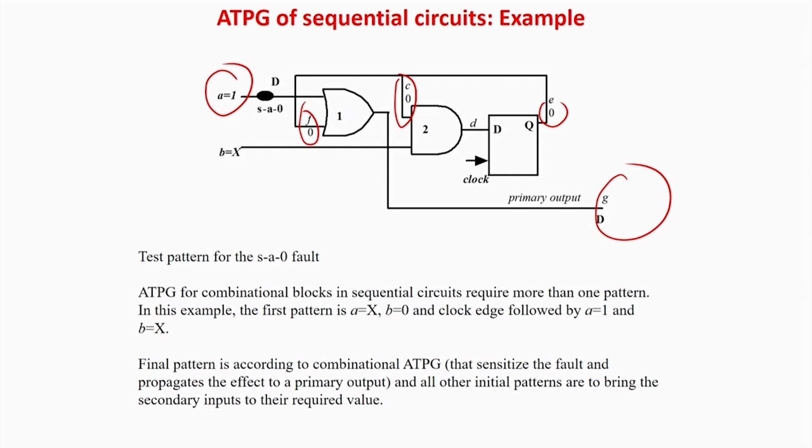So this case is very similar to a combinational test pattern. The idea is, if all the flip flops are set to their required values, which is required to do the testing, once you have settled the flip flops to their values, after that the testing of the fault will just become a simple automatic test pattern generation problem of the combinational circuit. Like if when f is made 0 by the previous step where b was made 0, now it becomes a combinational circuit problem. That is, you have to apply a 1 over here, it is sensitized, d, t is propagated over here, and already you have justified it previously by making f equal to 0.